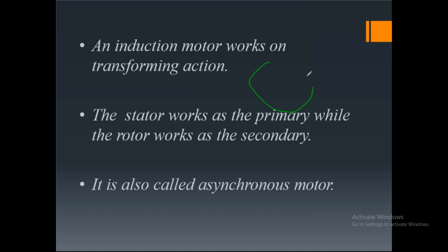So this is the stator of the three-phase induction motor, and it is the rotor. Now, when we apply the three-phase supply to the stator, due to this excitation an RMF is produced, that is the rotating magnetic field. So keep this abbreviation in mind. RMF is the rotating magnetic field, and it rotates in the gap between the stator and rotor. And the speed of this RMF we represent in terms of synchronous speed. So the rotating magnetic field is rotating at synchronous speed.